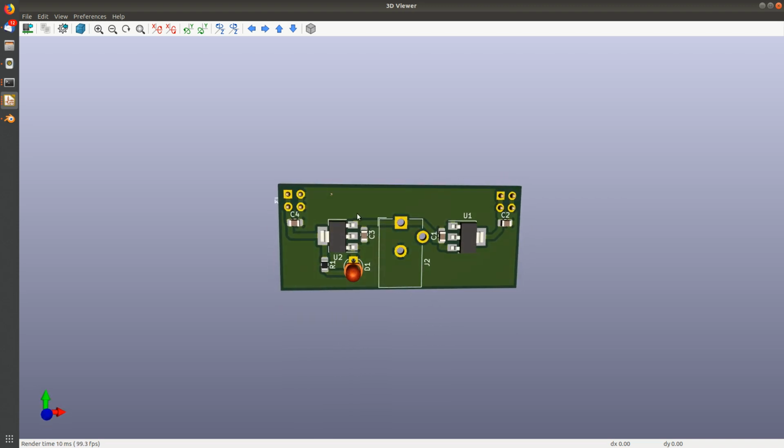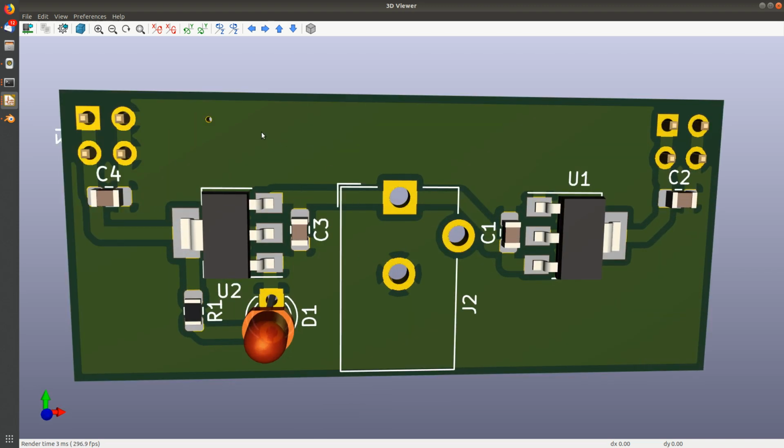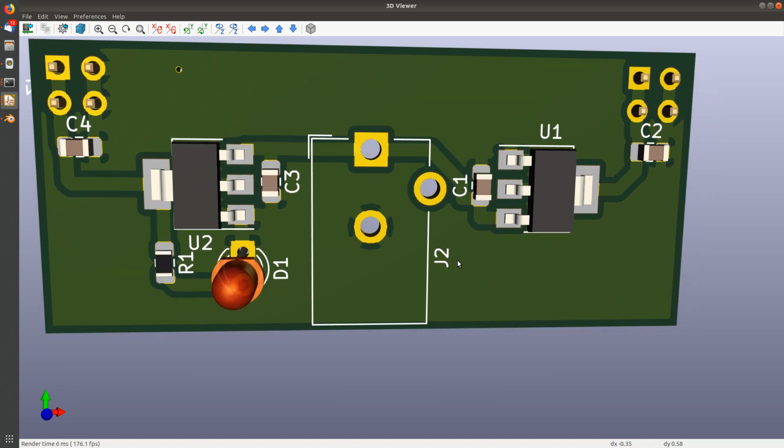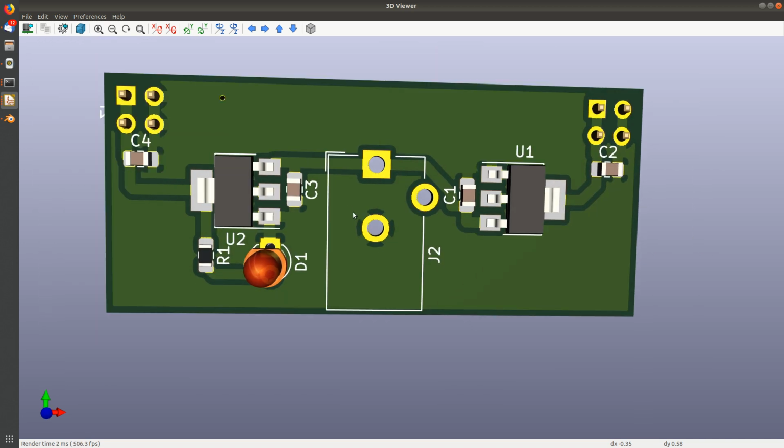Okay? Now, the reason you put vias on these boards, again, you don't really need to do it. This is 10 tons of overkill, but it looks kind of cool, maybe. Normally what you want to do is put vias around the outside of your board to connect the ground planes together. You do that because this is a pretty simple DC circuit. There's no real reason to do it. It'll work fine either way.